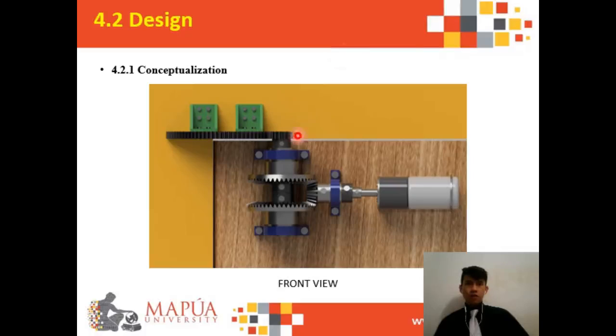The driving shaft allows two-way rotation. The motion rectifying mechanism consists of two bevel gears and one bevel pinion. The two bevel gears are set up facing each other.